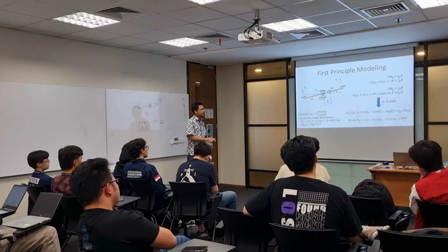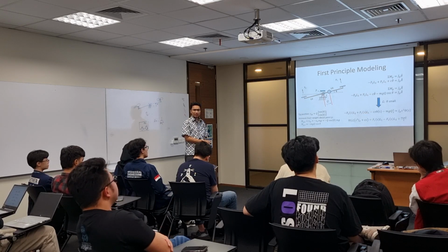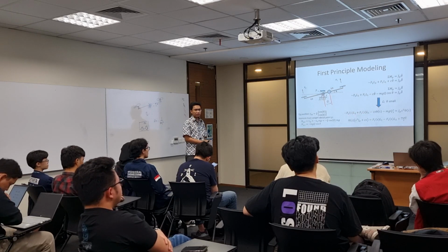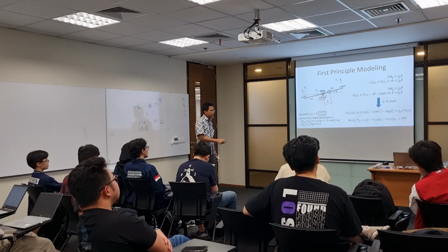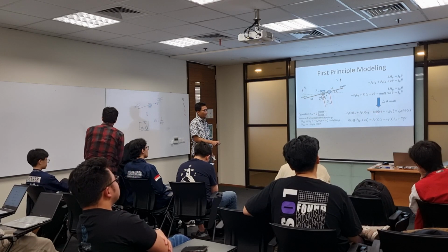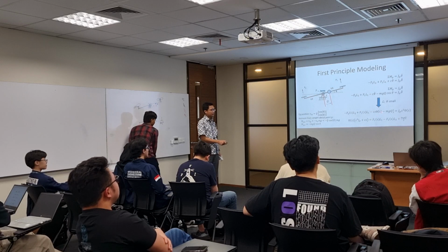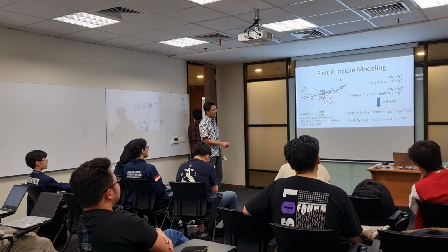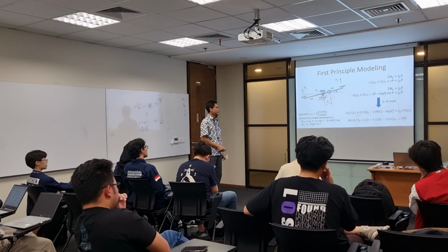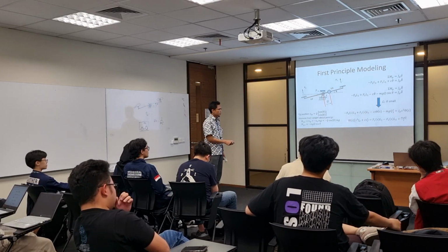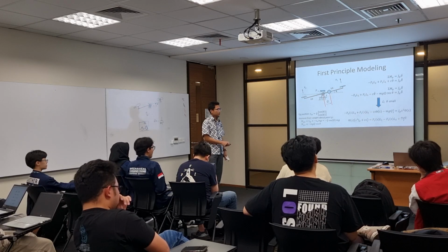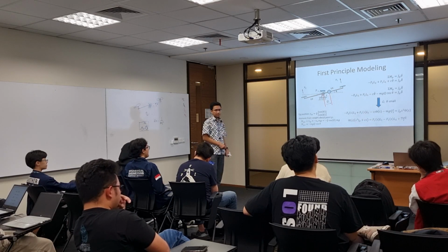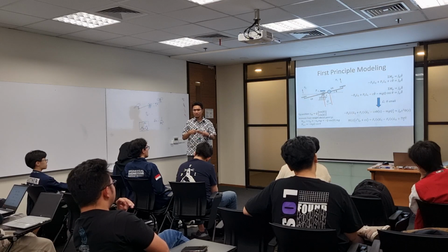The rest of the terms, I have F2 of s, F1 of s, and these are the thrust coming from the propeller. And this is the uppercase theta in s, which is 1 over s squared. So we get to the last line of the equation. Can you guess that this is the denominator of the transfer function?